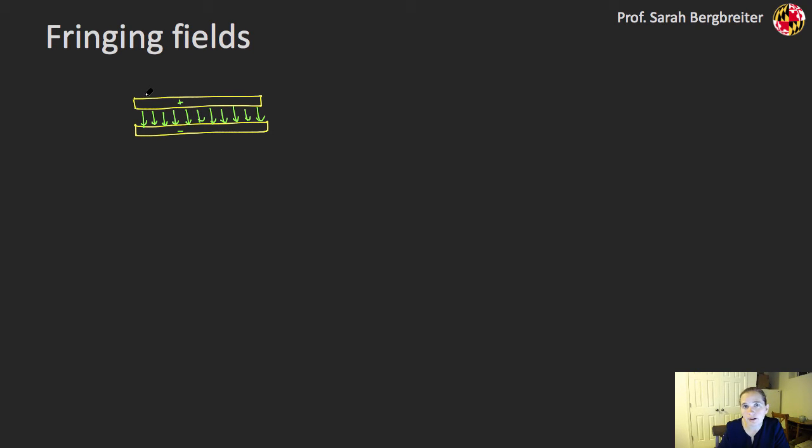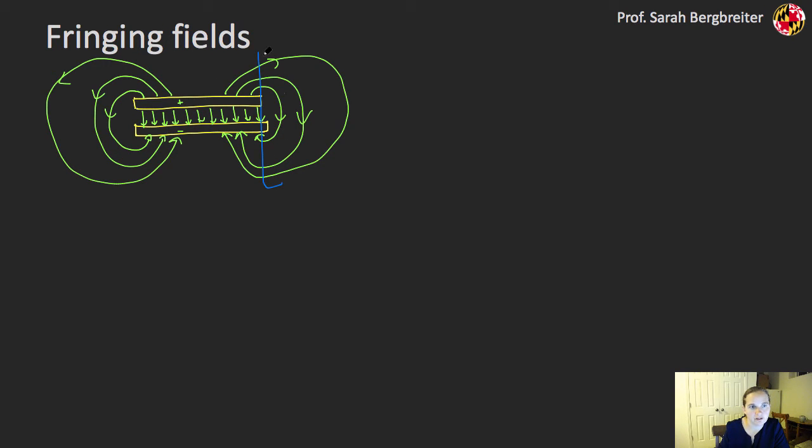But you also have what we call fringing fields. So I also have field lines that go like this around the sensor. Pretty much all the stuff out here, outside of my plates, I think of as these fringing effects. Unlike the parallel plate model, these fringing effects are really difficult to model appropriately, but I can think about how I would design sensors to take advantage of them changing.